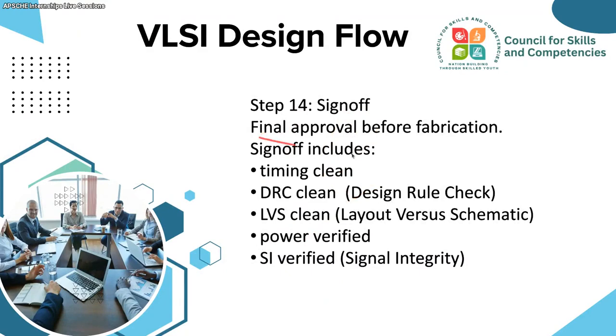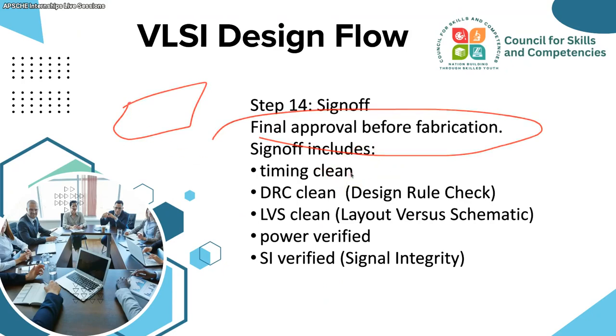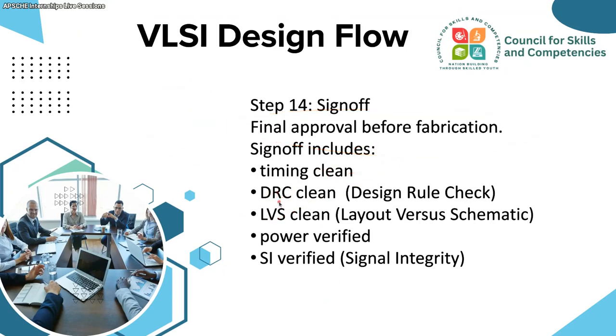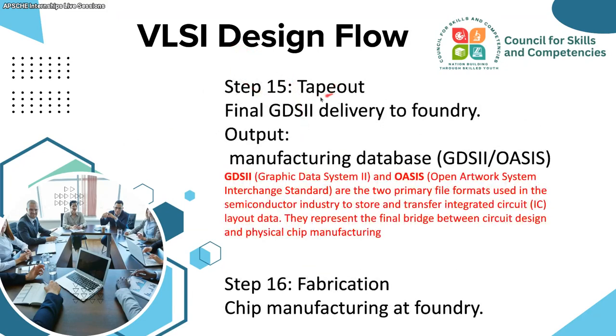the final approval before fabricating. Before fabricating into a chip, the final cleaning. Already we have done DRC and LVS. Now they want to go and clean: design rule check, layout versus schematic, power verification, and then signal integrity. They will go and check those things. Now the tape out.